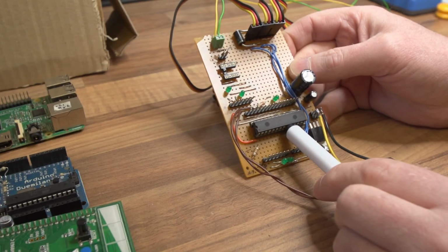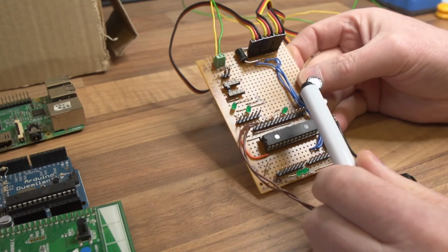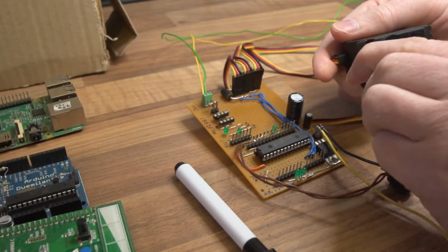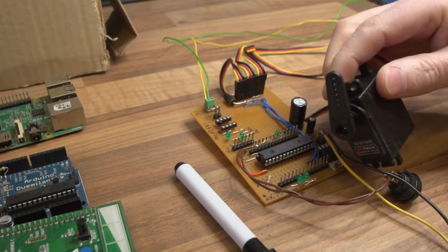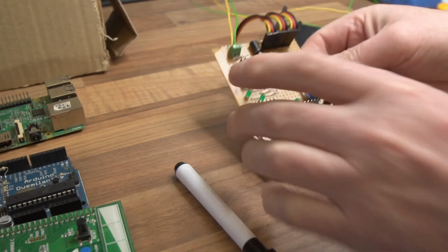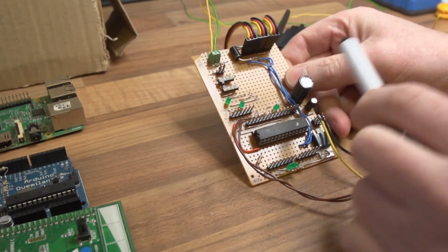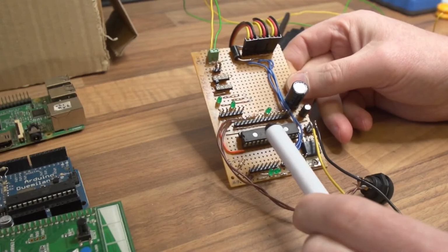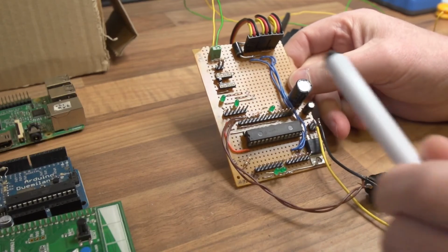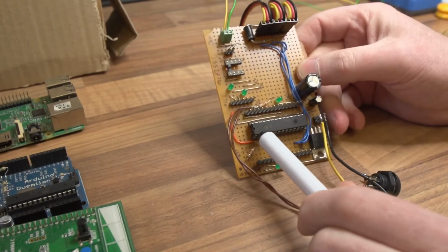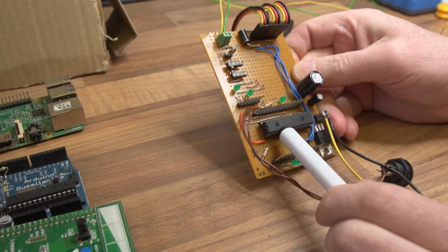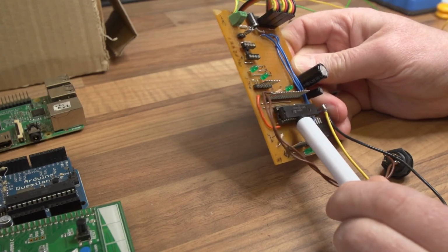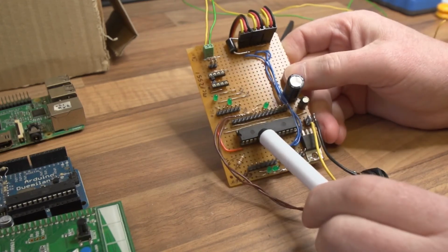But this particular one I put on a circuit board a while ago to make a pan tilt system to move a camera around on a tripod using these remote control position motors. This has got firmware running to drive those motors. It operates through CAN bus from an external device, so basically it's like a remote control to alter the motors. That's the task of the board. But the main thing here is the actual chip, and this particular one is a PIC 18F, I'm forgetting the number, 2585 I think it is, made by Microchip.